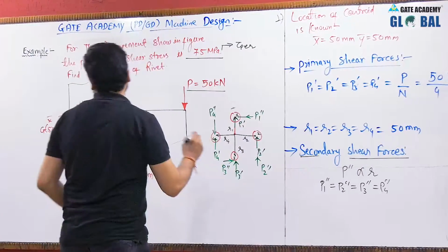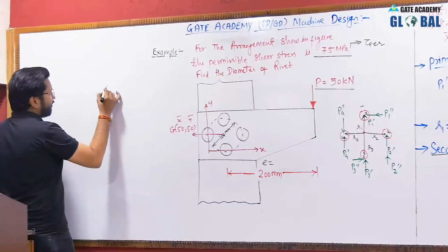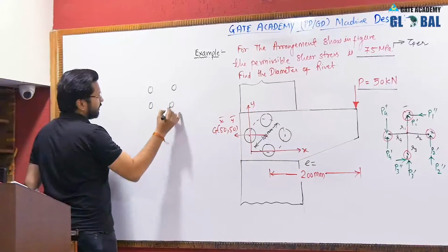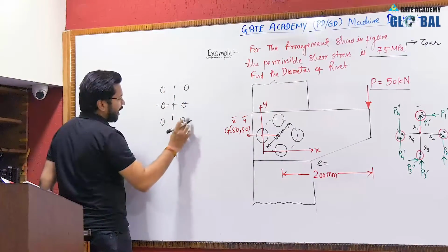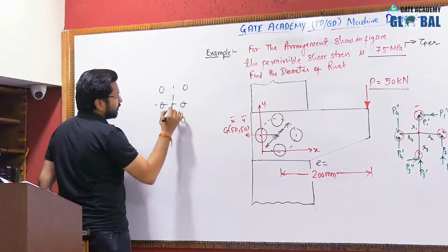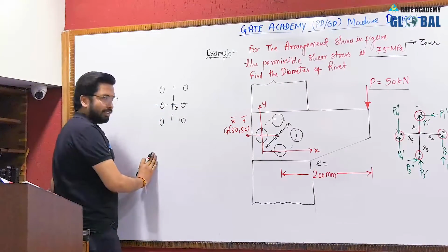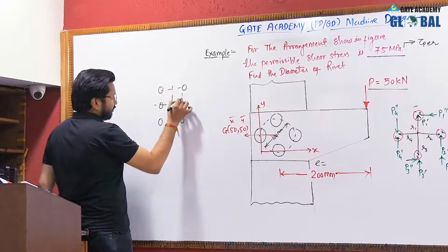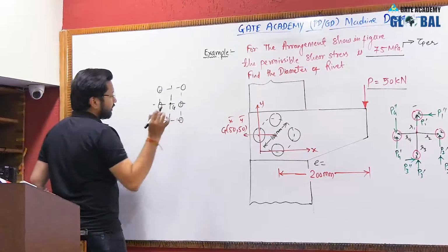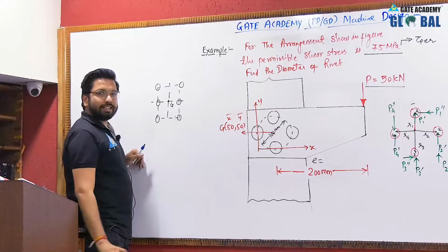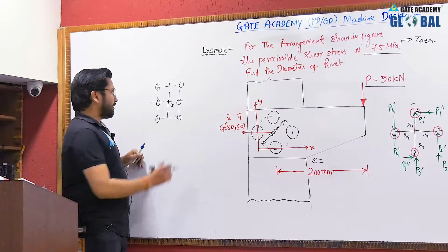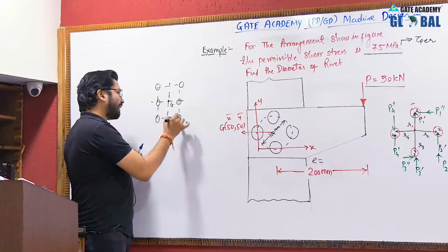Okay, like this, if there will be 6 rivets in the connection like this, okay, and this, then definitely this will be the centroid. I am just giving you an example. Okay, so this is the centroid of the arrangement G. Now this is basically arranged along the perimeter of a rectangle. All the rivets are being arranged in the perimeter of the rectangle. Then these are the extreme edges.